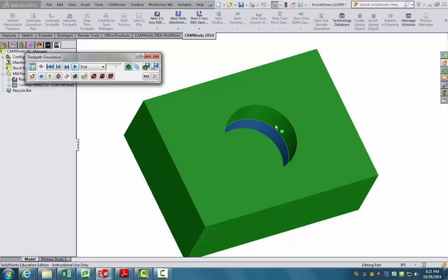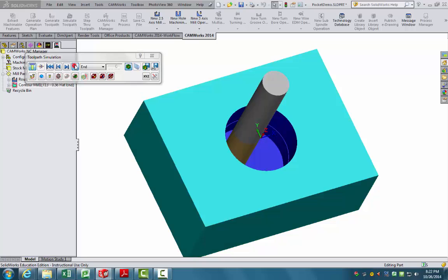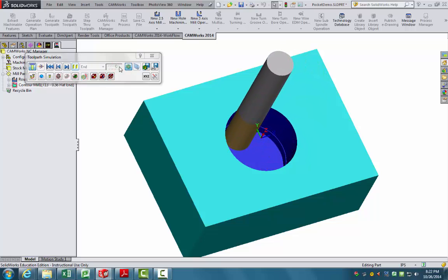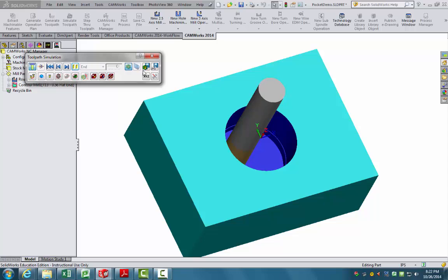This is a very common machining practice. You take a lot of the material out. Sometimes tools can be under high load or high stress. They can bend and flex, and they won't cut as accurately. Whereas when cutting a very small amount of material, tools generally hold their shape better and cut much more accurately. So by letting this finish, it is going to completely and perfectly cut out our part in the simulation.